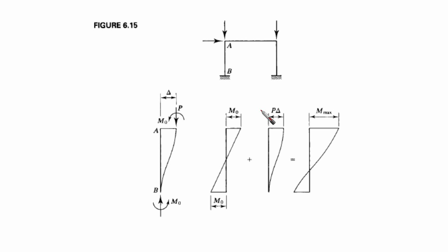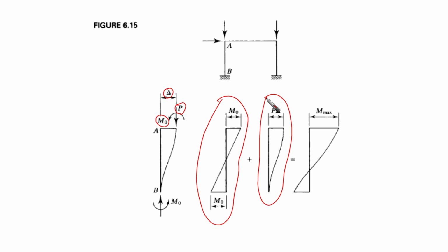Okay. In our case here, whenever we are looking at how this P delta effect is going to be taken into consideration, we have the column, let's assume AB for example. One end, which is end A, is going to move laterally with delta, and the axial force and the moment that is being applied on the element, which is P and M not, is going to be applied, and we are going to find that this can be decomposed of two parts together.